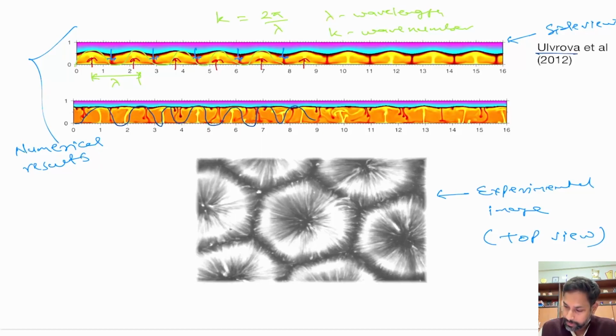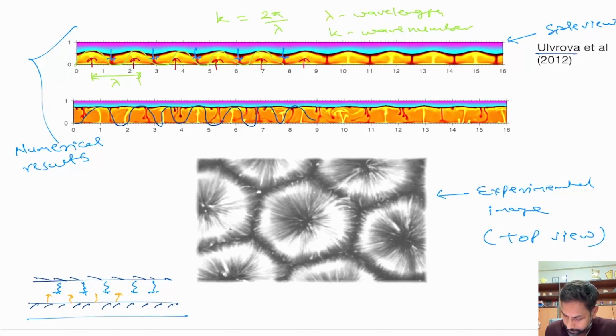And this is for a particular case where we assume that there are solid surfaces, and there is a convection happening from bottom to top and top to bottom, right? And in this case it is assumed that the horizontal length scale is like infinity. So we are not really considering how wide it is horizontally. We are only worried about how thick it is, or what is the gap between these two surfaces. Okay, so this experiment was performed by Benard himself.